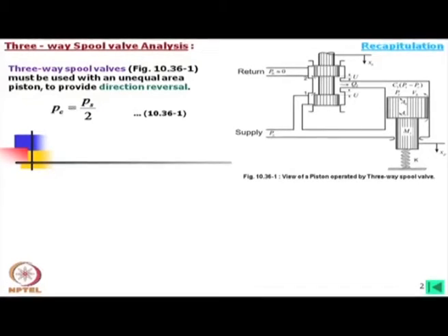So, for position control as well as force control, it is always better that there is pressure from both sides, and that is why you will find in servo control there is pressure on both sides. Obviously, there will be loss, definitely there will be flow and pressure loss, but from the control point of view this is unavoidable.